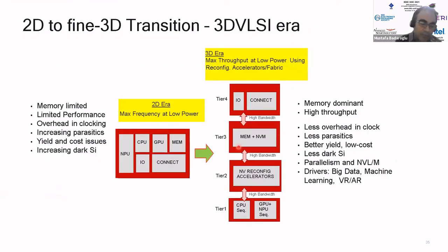Because we cannot put the CPU below the memory that effectively, but if we employ a parallel architecture, for instance, doing a controller below and then putting a non-volatile reconfigurable accelerator, it can be like a compute unit, like a MAC unit on top of the sequencer, and then several memory tiers where the data moves naturally vertical in this direction to create a multi-tier stacking system.